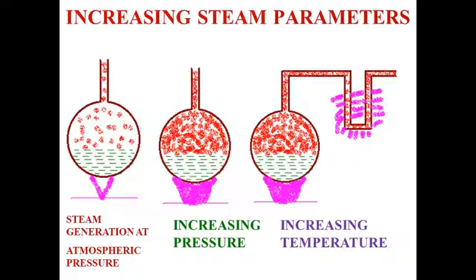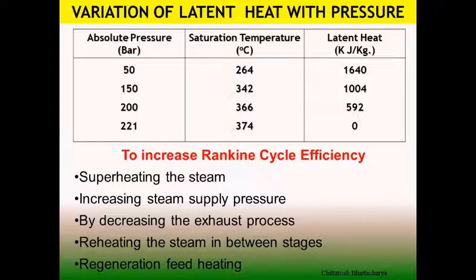So that creates film boiling, and film boiling is critical for tube material because there may eventually be a higher temperature of the tube metal surface and there may be failure. So we have to see how we arrange the heat addition successively so that the tube metal temperature is not getting higher and damaging the tube by high temperature oxidation.